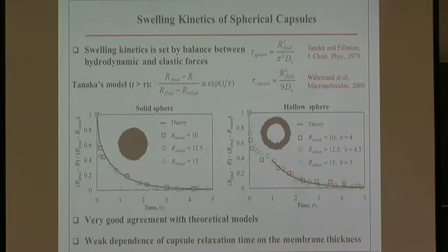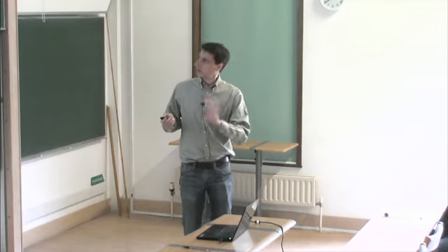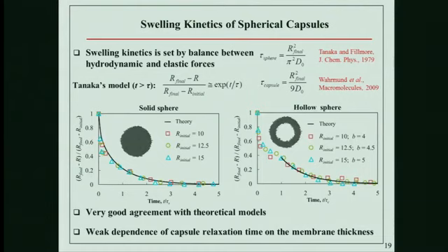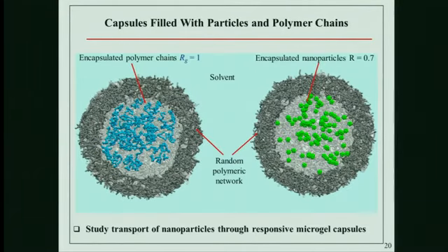So essentially, this simulation tells us that we not only capture the transport properties correctly, we also capture the mechanical properties correctly, because this collective diffusion is a function of elasticity, a function of the modulus of the network, right? Essentially, it gives us the balance between elastic forces and transport properties. Okay, so we validated this part, so let me show you how we can model the release.